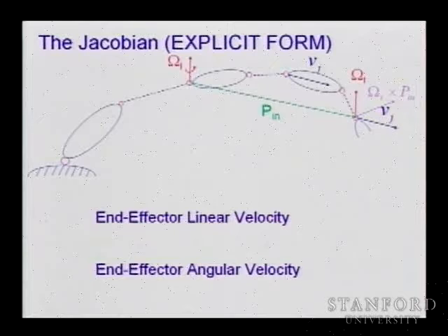And we will see that essentially this Jacobian is really related to the way the axes of this robot are designed. And once you understand this model, you are going to be able to look at a robot and see the Jacobian automatically. You look at the machine and you see the model automatically, through this explicit form that we will develop to compute those linear velocities and angular velocities through the analysis of the contribution of each axis to the final resulting velocities.